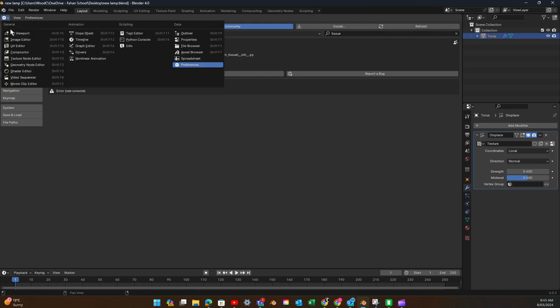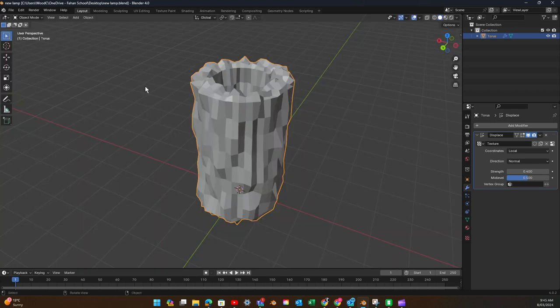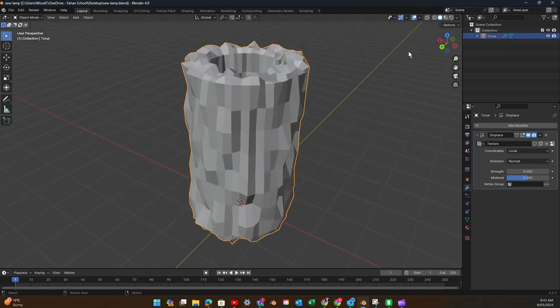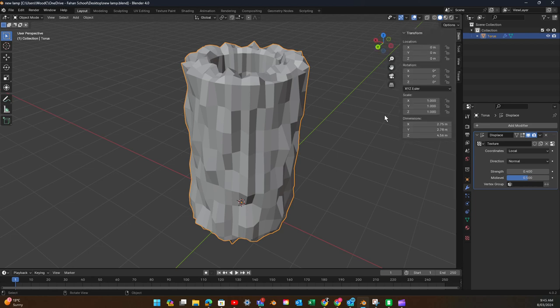So all I've got to do is go back to the 3D viewport now, have a look around, we're looking good, and there's a little button you can use there to pull out the tissue plugin, or you can hit the M key, which is what I tend to do, and that'll bring out that tab, and we can click on tissue.